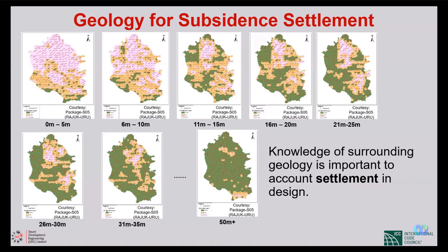The thing is that we do not consider the settlement issue for the subsidence that is happening due to groundwater depletion. To account for that settlement, we need to have a pretty good idea about the soil profile at different depths, because we are going to put the footing of a building at different depths depending on the load demand. So knowledge of the surrounding geology is important to account for settlement in design.